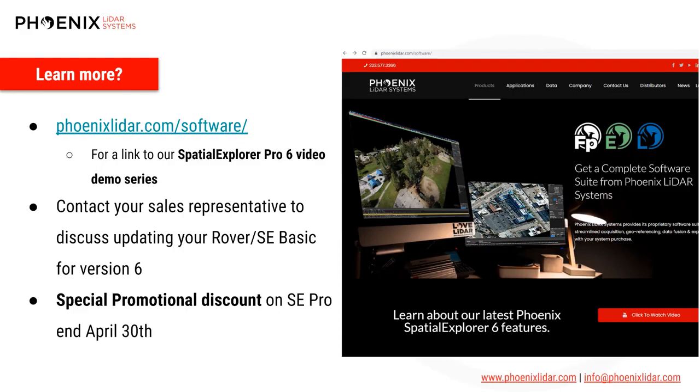What about the Nuvlab portion that's in SE Pro? Ben? That is the LiDAR mill Nuvlab. If you go back to that slide, that is the LiDAR mill logo, and the idea is that you can use your LiDAR mill account to compute trajectories. So all the data, reference stations, rover, so raw GNSS and IMU data will be uploaded, trajectory will be computed, and then downloaded and reintegrated into your project.